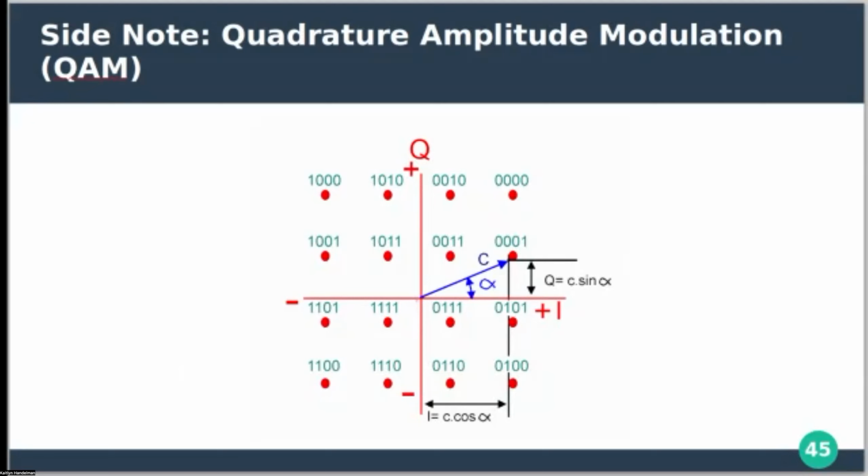And in fact, what your Wi-Fi router is doing behind the scenes is it's looking at the signal strength and then deciding, okay, the signal strength is really bad right now, so we'll use like 2 quadrants. Or now the signal's starting to improve, so we'll use like 4 quadrants so we can get double the data. Or you'll get a really good signal and you'll get, oh my gosh, 64 bits of data per quadrant because we got a really good signal, no noise, perfect.